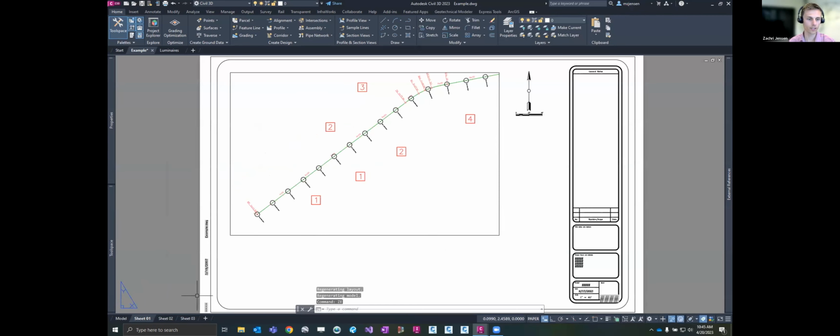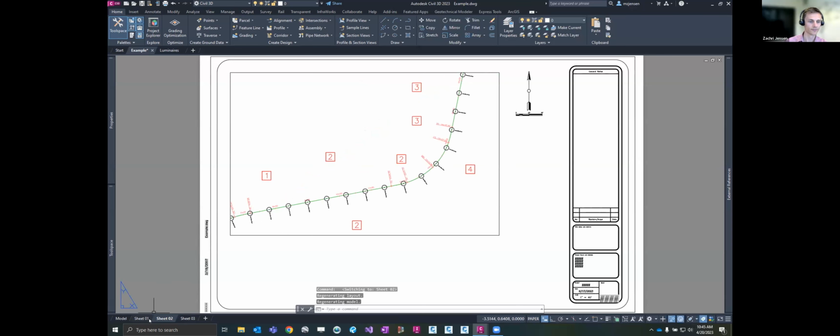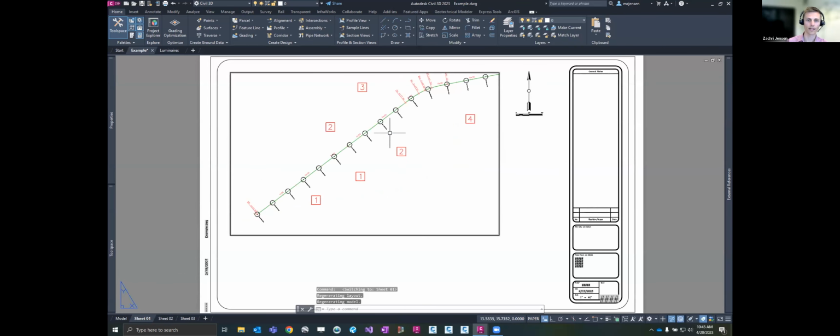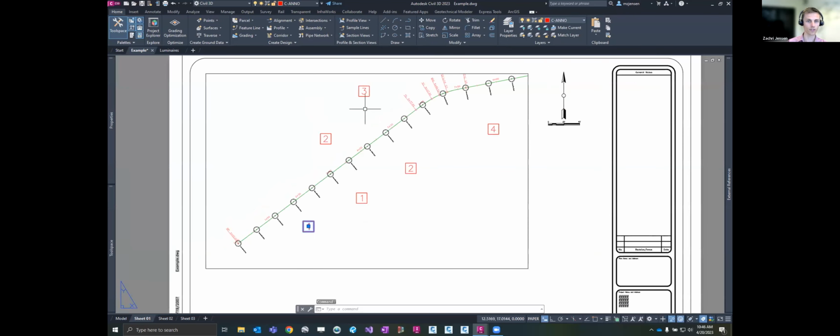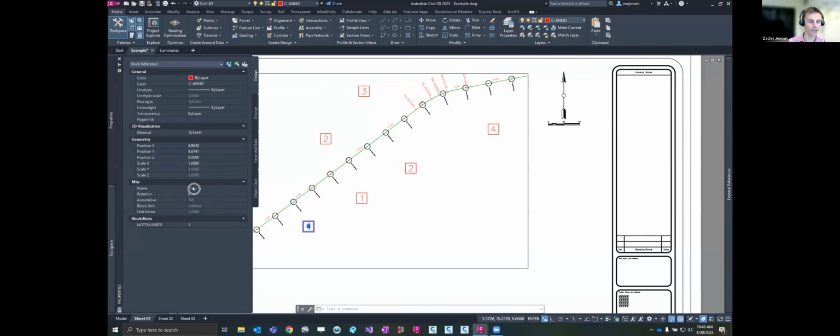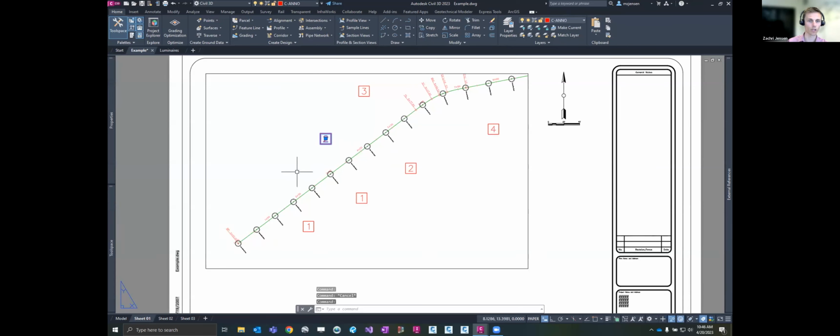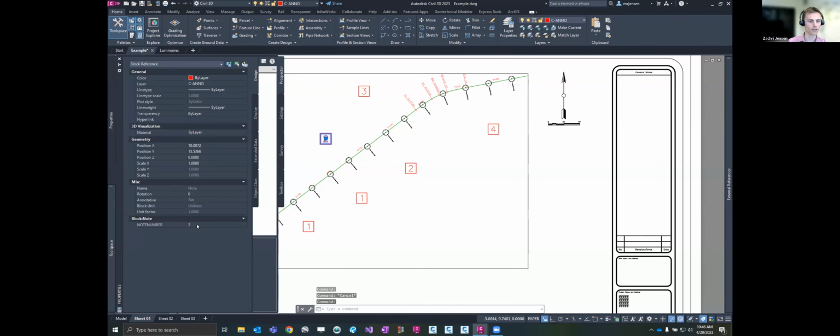What I have here, I have three sheets, very basic. Just got a viewport back into our model space world. And then I've placed these very egregious and kind of ugly notes everywhere. And they just have numbers in them. So these numbers are attributes. Okay, so this is one block. The source block is just called note. And then I have an attribute called note number in that block definition. And then each one of these block references has a different value assigned to those attributes.